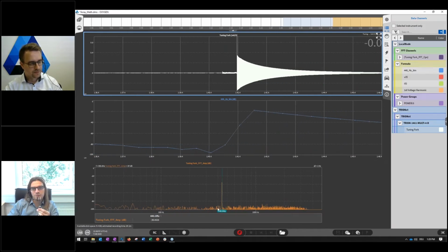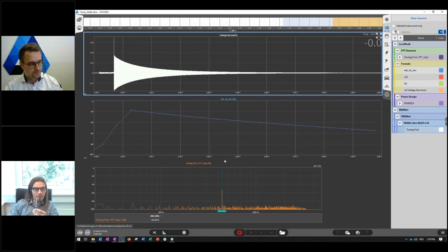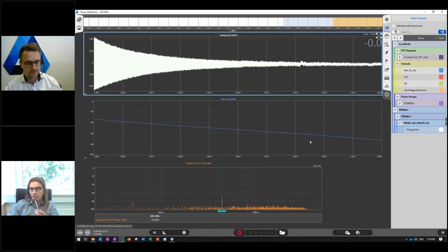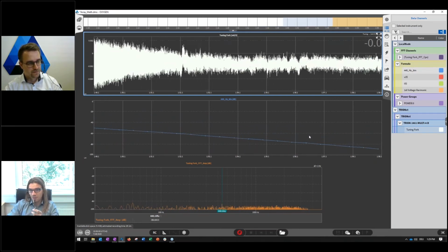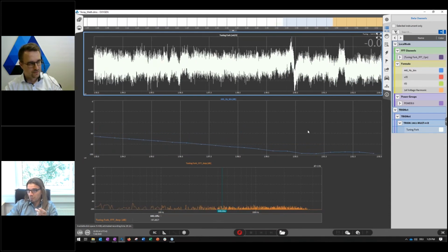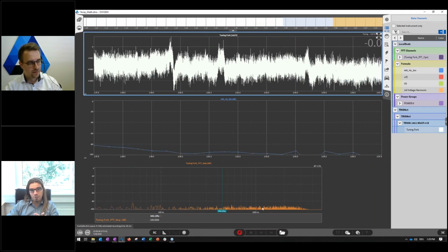And you can now use the array math to extract this frequency bin into the time domain and to visualize it like you see it here in the recorder in the middle. And you can now also use an FFT trigger here to start the measurement automatically when this 440 Hertz frequency bin exceeds the amplitude of -40, for example. I will show you this quickly.